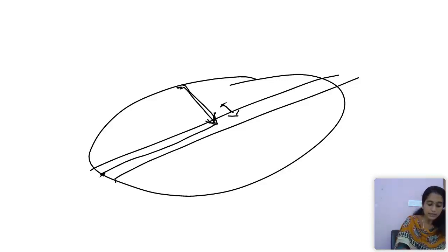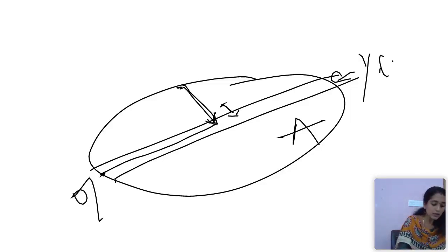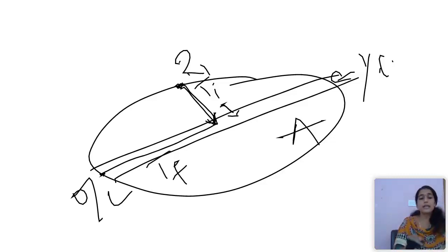This is a particular catchment area A, and this is the inlet and this is the outlet. This raindrop R1 should reach the inlet, and then travel through the sewer pipeline up to the outlet. That is T inlet, Ti, plus Tf, is the time of concentration. I hope you understood the concept of time of concentration.